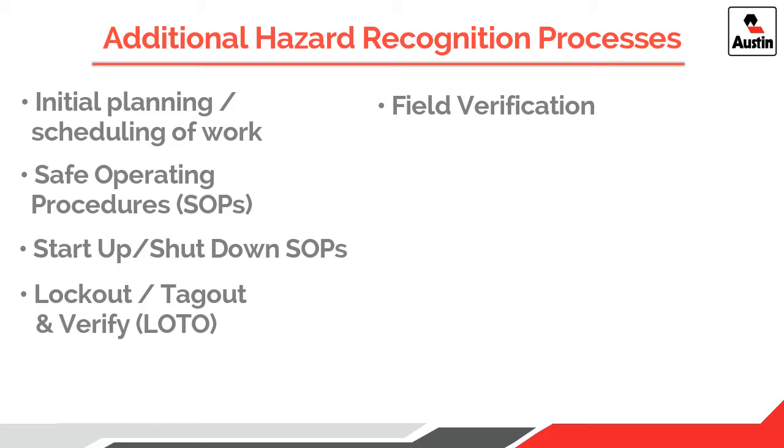Initializing and following all safe work permits for the jobs that we are carrying out. Safe work permits can include hot work, line break, confined spaces, and excavations. A permit is a way to ensure that we have performed all safety requirements before performing these critical jobs. A JSA supports these permits, it does not replace them. Performing a JSA for every job and task that we perform. Remember, no task is so minor that it does not need safe planning.